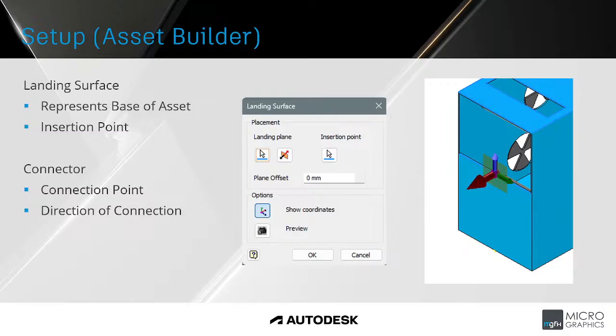For those of you that are not too familiar with the Factory Design Utilities, essentially when you create a factory assembly, you have a ground plane, and anything that you bring into that assembly will want to snap to the ground. Now, for a piece of equipment to snap to the ground, we need to specify its landing surface. So this would be the foot of the object, so the feet that it's going to stand on.